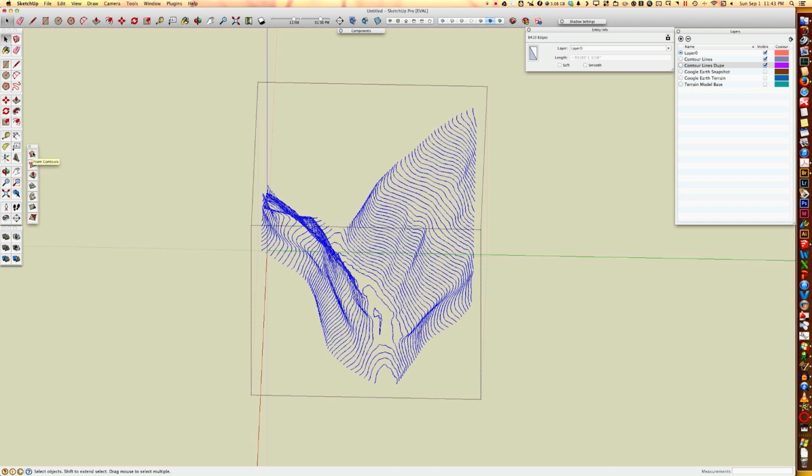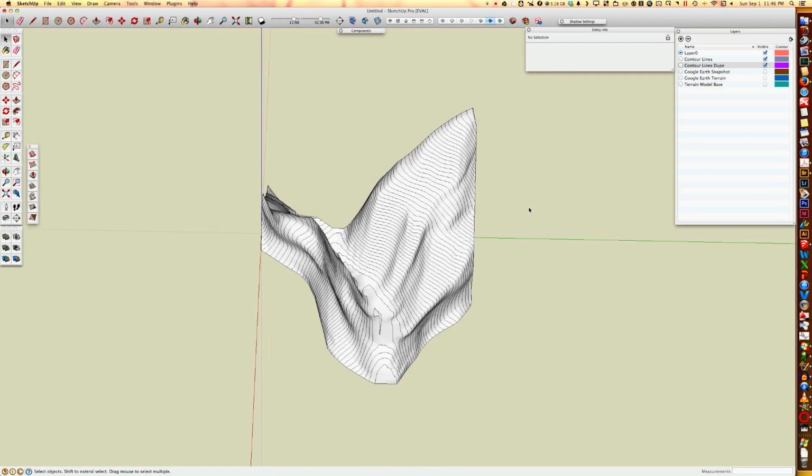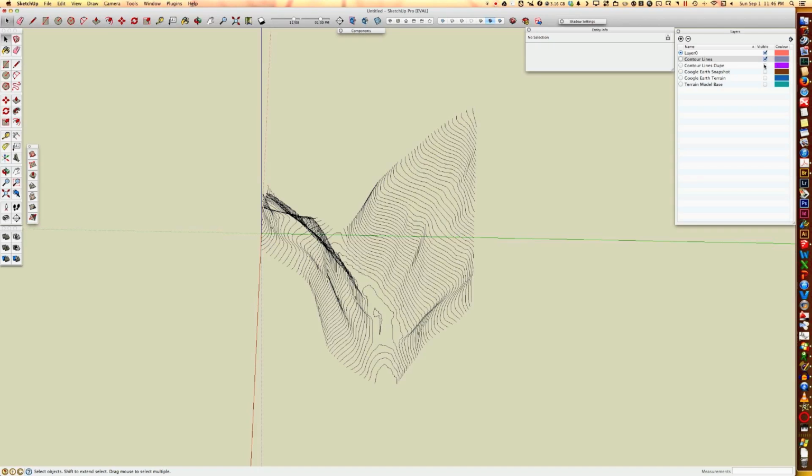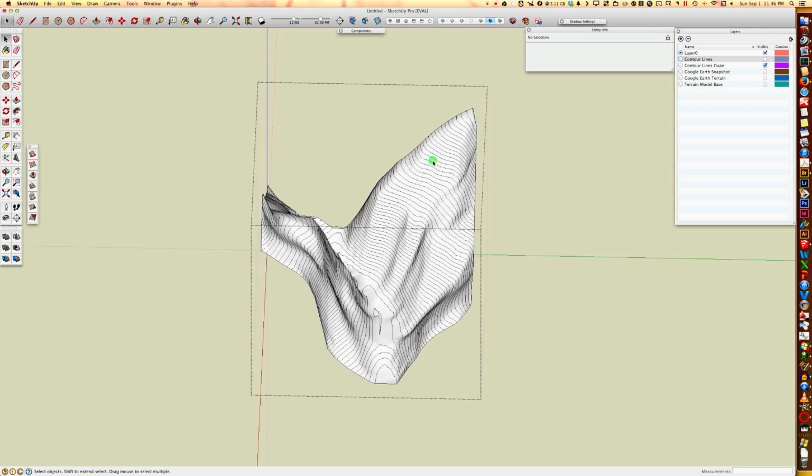And the top tool is to create a surface from contours. So we're going to run that routine. And this takes a few seconds here. So I'll probably cut this out of the video. Alright, so that took about 2 minutes to do the surface. And you'll see now, I'm going to turn off the contour lines, that what we have, actually I have to go back to my group here, that actually got created inside of the group here.